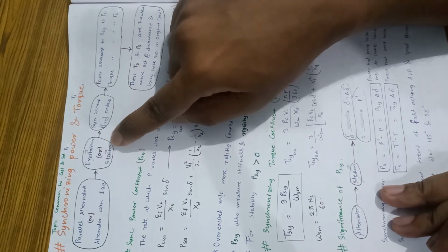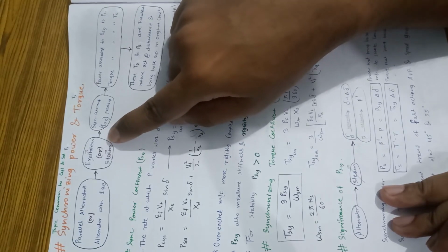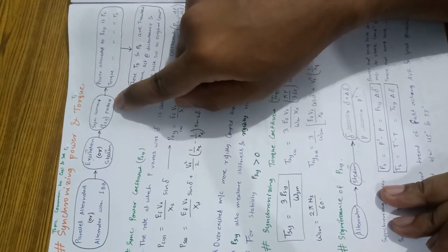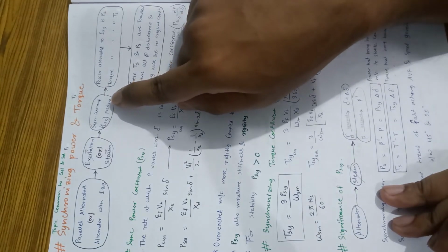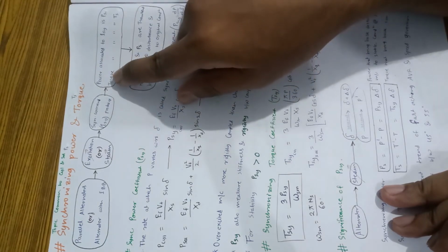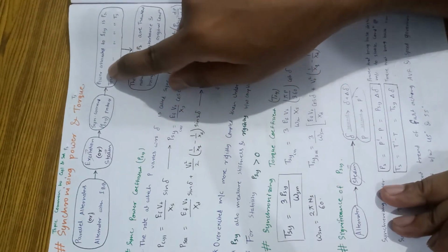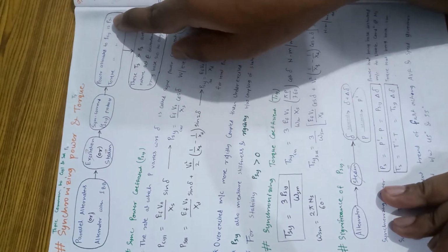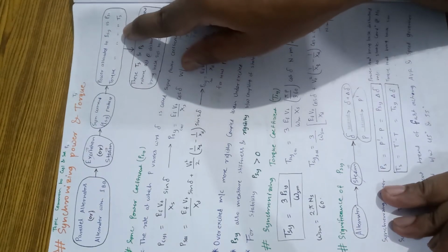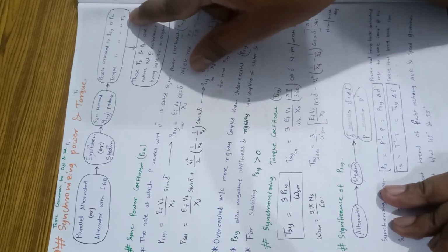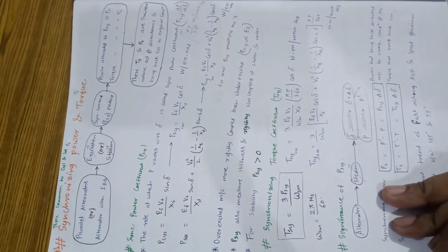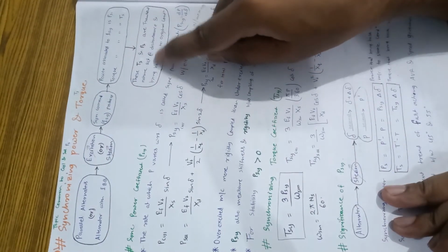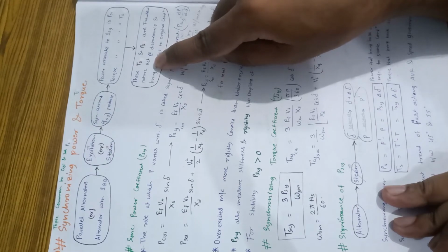In either case, a synchronizing current, that is Isy, is produced. This synchronizing current will lead to power and torque. Power associated with the synchronizing current is called synchronizing power, and torque associated with the synchronizing current is called synchronizing torque. This Ts and Ps, that is synchronizing torque and synchronizing power, are transient in nature, and act